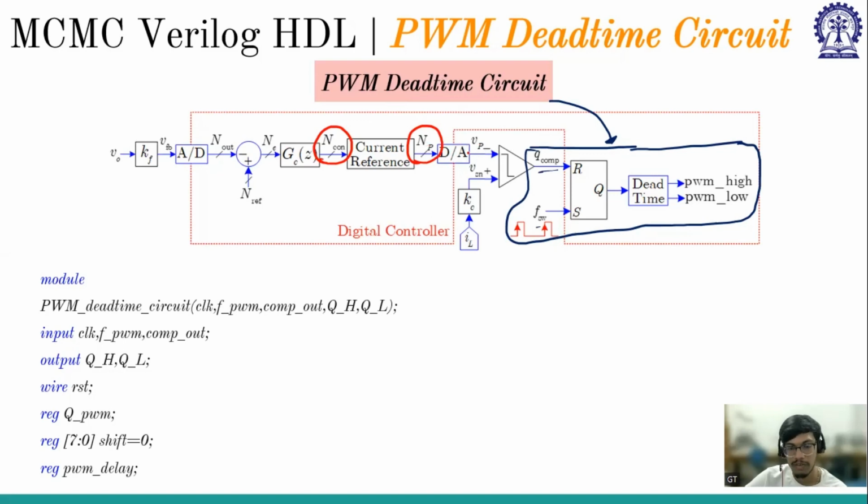So that's why they are using offset binary, not 2's complement. Whereas the ADC, they are using 2's complement because they had made the 2's complement ADC, and it can also be offset binary. There is a provision. You have to connect the circuit in such a way so that you can access 2's complement also, and offset binary also. But DAC, they are making only offset binary, so that's why we had to give offset binary. Had it been only 2's complement, then we had to only put saturation limit, match the Q format, and send it as it is. But because it is offset binary, we have to go offset binary.